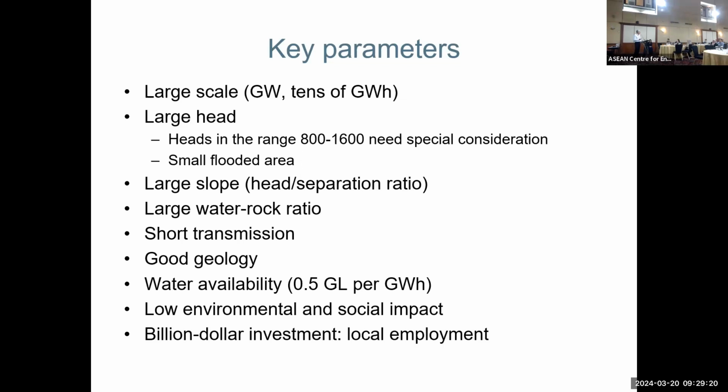Obviously, you need good geology, and you find that out when you do the pre-feasibility drilling. The fact that there are thousands of good sites means that if you come across a very bad rock, you don't need to try and work around that. You just go to another site. So unlike in a river system where you have very limited number of sites, here you have many sites and you can walk around a problem rather than solve it.